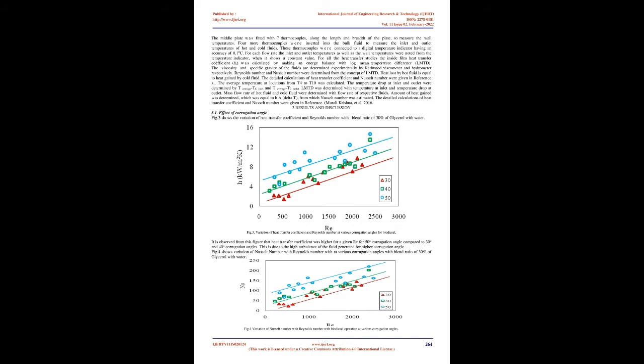Lin J. et al., 2007, used the Buckingham pi theorem to study dimensionless correlations to characterize the heat transfer performance of the corrugated channel in a PHE. They substituted the experimental data into these correlations to identify the flow characteristics and channel geometry parameters with the most significant influence on the heat transfer performance. They observed that the dimensional analysis reveals the local Nusselt number, Nux, is determined primarily by R/dh, geometry, X/dh, location, and